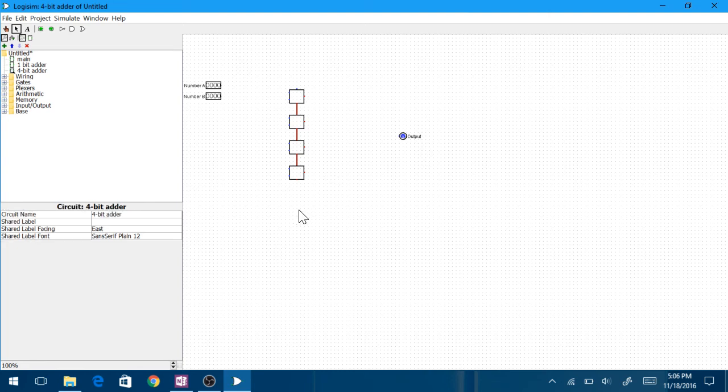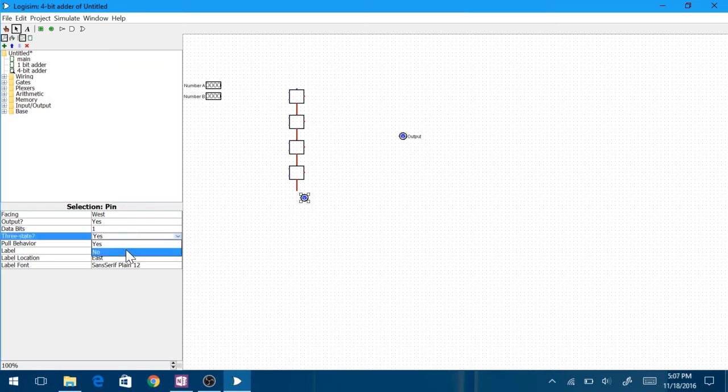We still have to worry about overflows. Remember how I said the leading bit indicated whether an overflow occurred? The last adder will always indicate the overflow bit, and there's always just going to be 1 bit. I'll change it out of 3 state. So we hook this up to our last adder here, and this is always going to tell us whether or not an overflow has occurred.